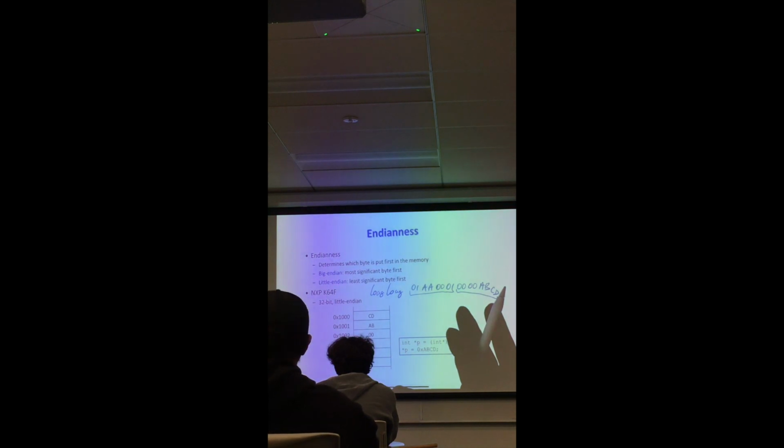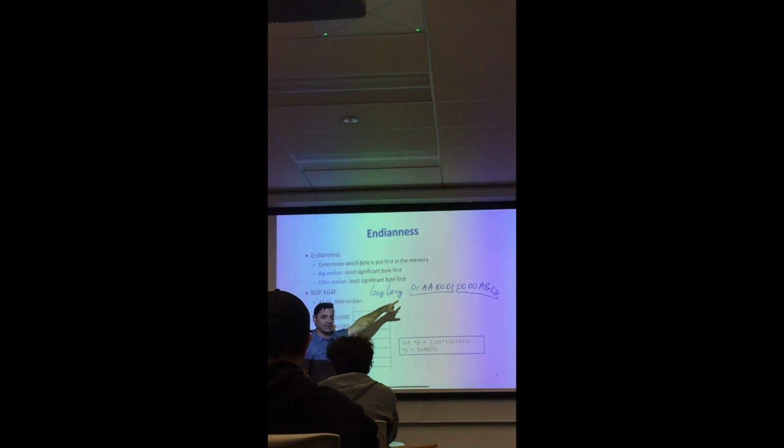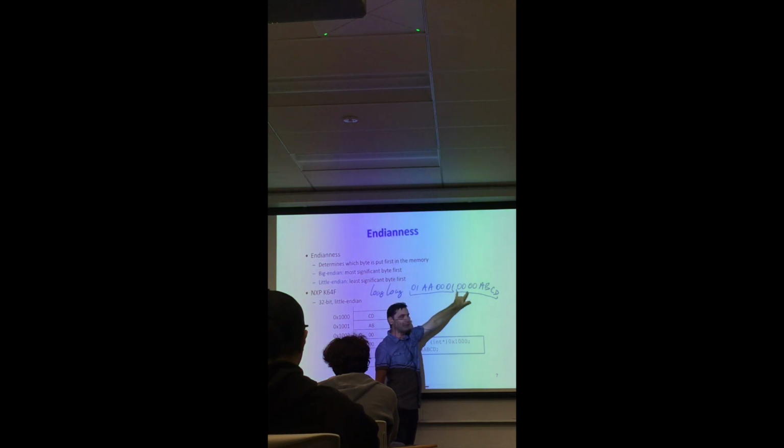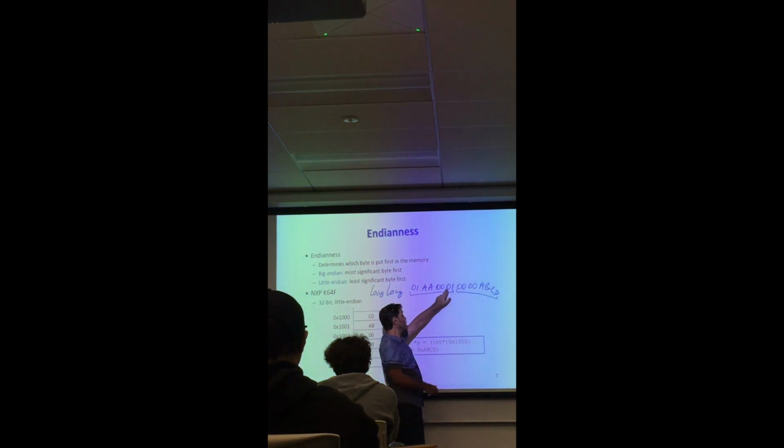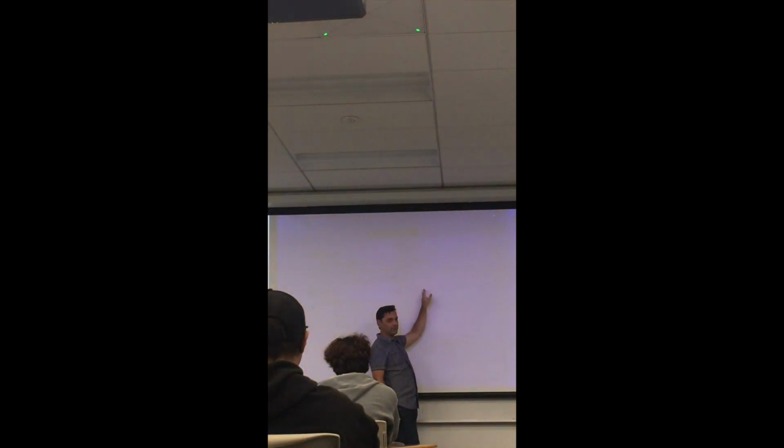Is that here? So if we do little endian, it's like a short-term, right? Yes. So it will actually write again, little endian. It will write the least significant byte first. So there will be no issues. It will actually write CD, AB, 0000, and then it will write that one also in that order. So there will be no issues whatsoever. You got it? So the little endian will never cause problems.